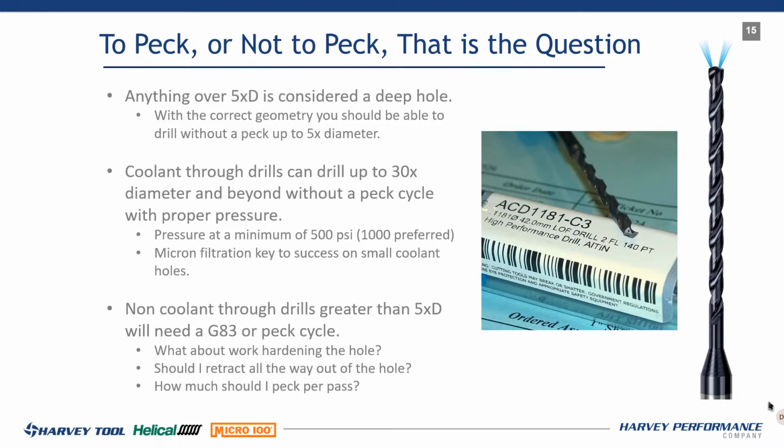So when people call me as applications and say, hey, listen, Don, I'm using a coolant through drill, and we probably have some application engineers on our team on this call, and guess what? It's not working, and I have to peck. Well, part of that is because we're not getting the shape of the chip we need, so the coolant can't push it up the flutes and evacuate it. And usually 9 out of 10 times, it's the wrong tool for the application or the wrong speeds and feeds, so we're not breaking the chip properly.